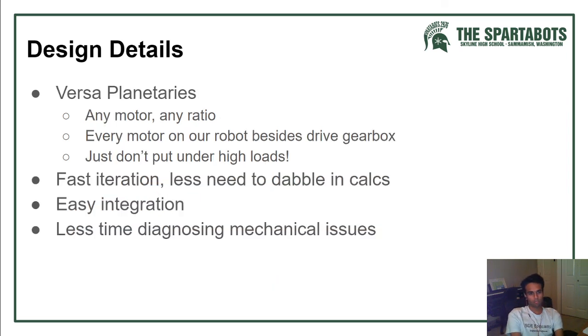And so, like I was saying, versaplanetaries, you can mount them on any motor, any ratio. Every motor on a robot, besides the drivetrain gearbox, basically, you can use a versaplanetary. Just don't put them under too high of a load. So a single versaplanetary is not going to be able to handle an elevator going all the way up. So make sure that they are in the right place at the right time.